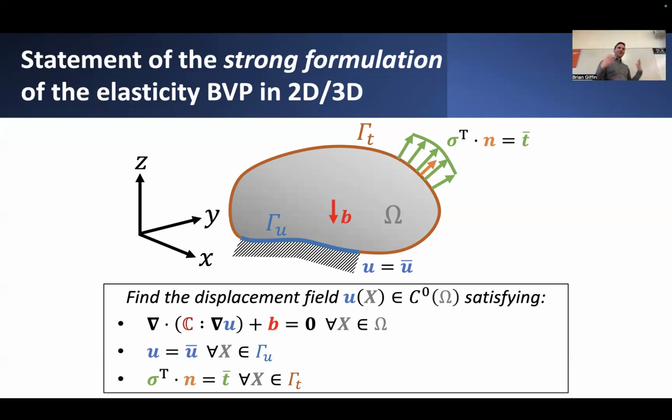So what we really want is to convert this strong formulation of the boundary value problem into a different format that allows us to, number one, convert it into an equivalent but simpler problem, which is to say a smaller problem, which we can solve in an approximate sense. And the other issue is we want to get rid of this term that involves having to take a derivative of whatever this term is. And remember that this term is really nothing more than the stress tensor itself.